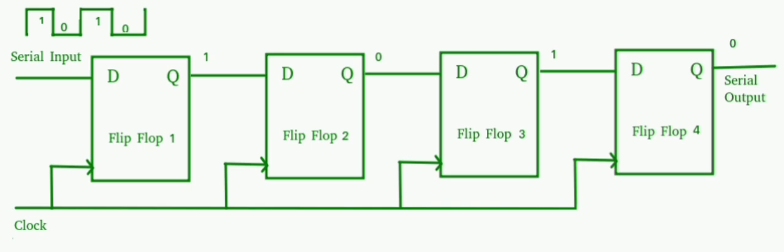If n-bit data is stored in a SISO register, then the output is taken serially. For this, n-1 clock pulses are required. A SISO register is used to provide an n clock pulse delay to the input data. If T is the time period of the clock pulse, then the delay provided by SISO is nT.